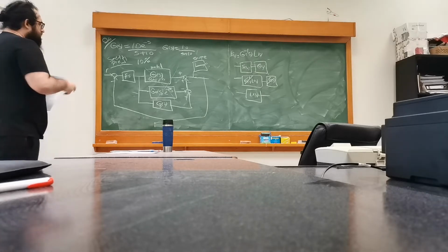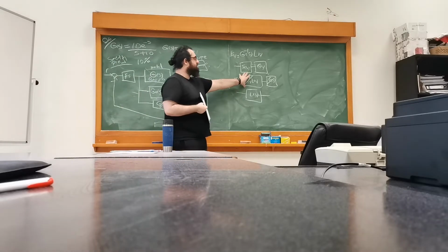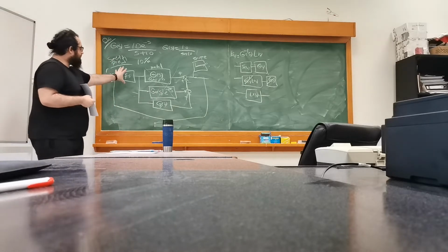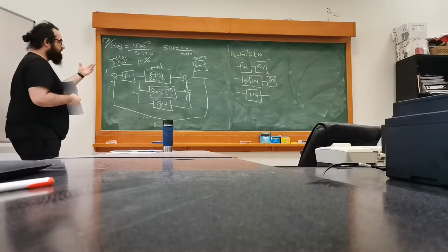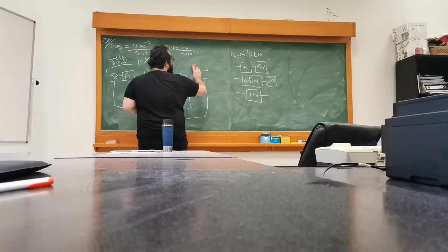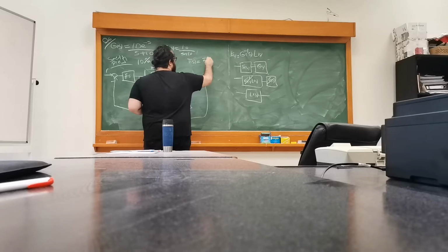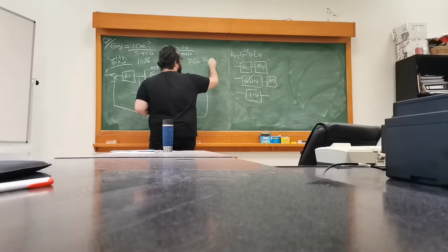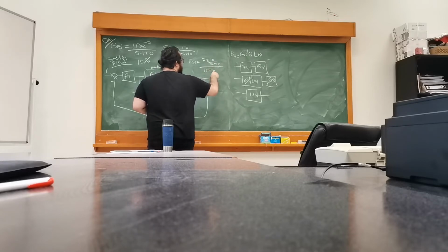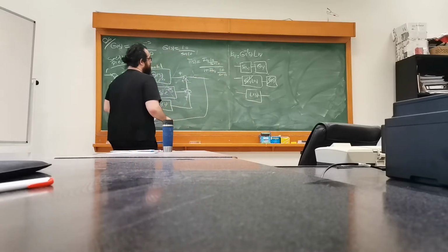So that's important. Once you achieve that, once the model is correct, if the poles and zeros match exactly, if you have the correct delay model, then you're left with F(s) times G0 divided by 1 plus F(s) times G0 here. So your closed loop transfer function becomes F(s) times 10 over s plus 10, divided by 1 plus F(s) times 10 over s plus 10.